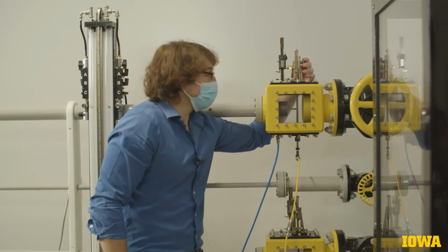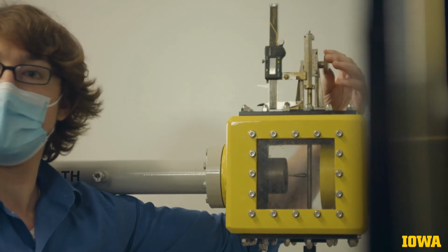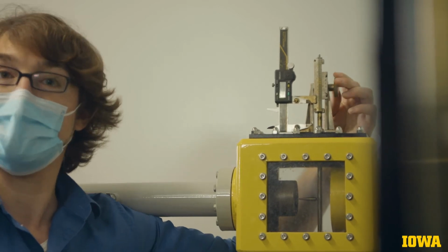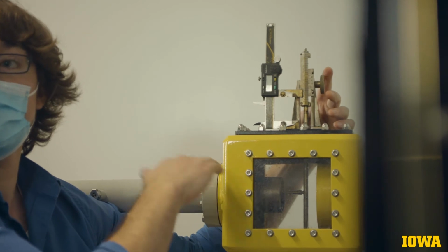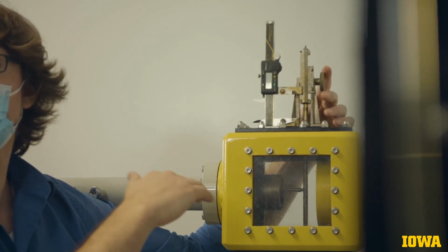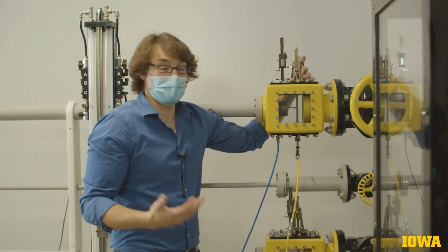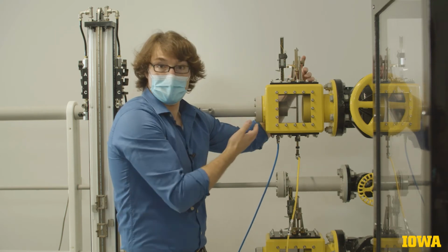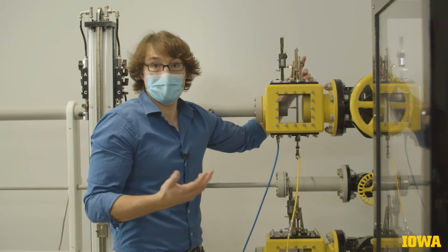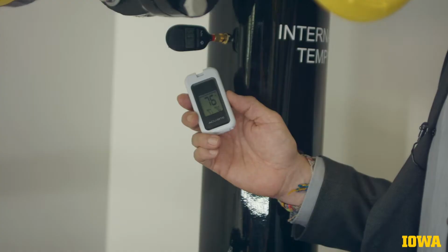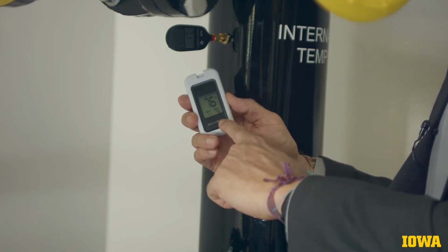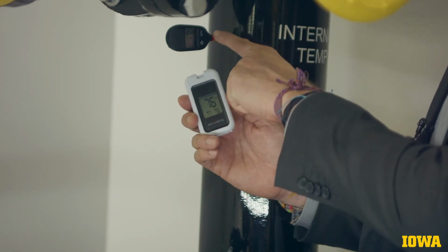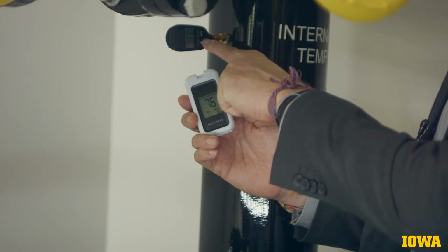Each of these pitot probes is equipped with a traverse that allows us to move it across the pipe's cross-section, and therefore allows us to measure the velocity at different points along the pipe's radius. We'll use this functionality to obtain a velocity distribution inside of the pipe, which will then integrate to come up with the total flow rate. Throughout the experiment, we will be keeping track of the temperature in the room and the temperature of the air that is moving inside the pipes.